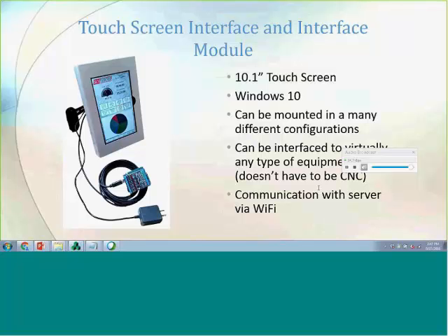They probably deal with thin client access and not being able to connect to a runtime application, and it's almost always related to IT constraints and getting ports correct, and understanding the difference between the web server and the TCP/IP server that serves out the tag data. So there's definitely some work you need to do to make sure it all works together, but there's nothing inherent about firewalls or the InduSoft solution that prohibits that. You just need to make sure that everyone's on the same page. Yeah, yep.